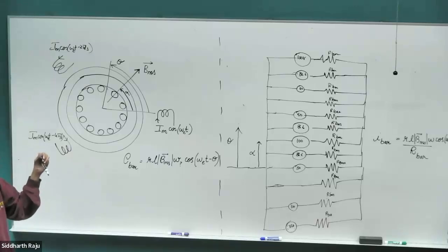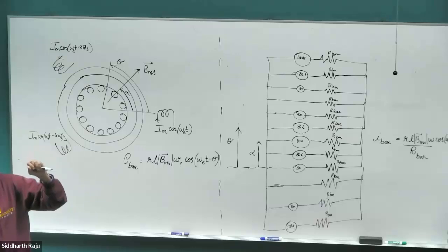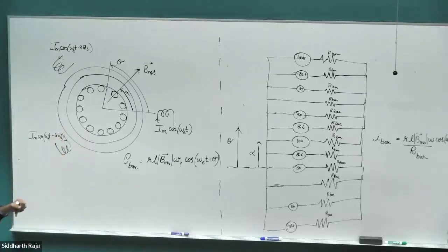And so what typically they had to do is on the rotor, instead of putting magnets, they put electromagnets. So you have to pass current into the field coil on the rotor to create the magnetic field, even for a synchronous motor. So it's not a permanent magnet synchronous motor, it's a field excited synchronous motor. And when we go to that, we again lose the benefits we got from moving from DC motor to AC motor. Right? Because to send current to the field coil on the rotor, you still need some kind of mechanical apparatus which can have mechanical isolation, yet still make electrical contact. We use, instead of a commutator, a thing called a slip ring, which is a full ring, and then a brush just brushes past it.